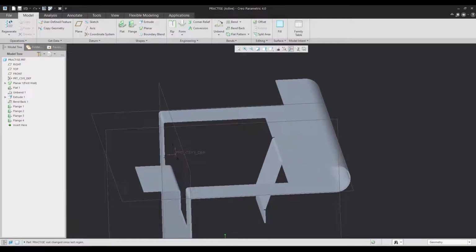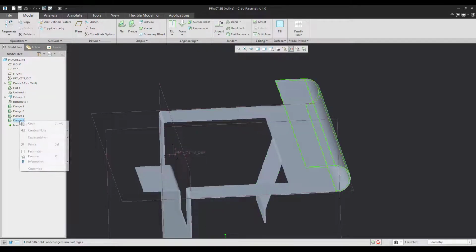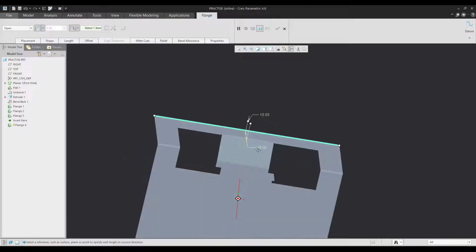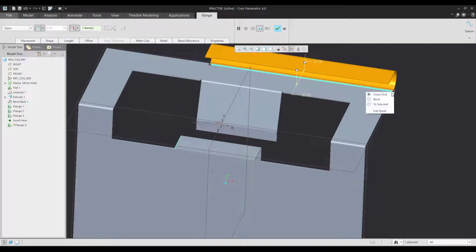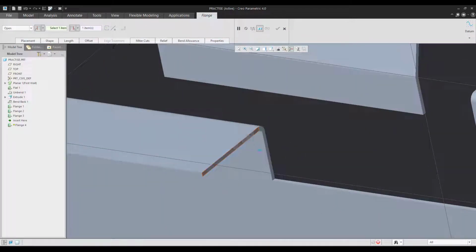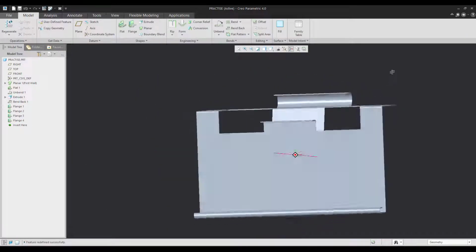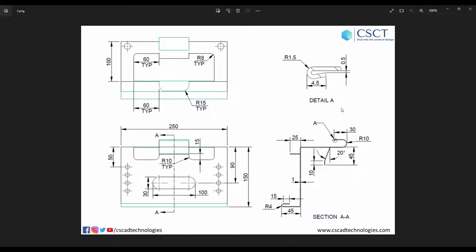Now, the whole wall is not throughout the body, it's just at this location. So, again, you can either give selected to the edge or you can give the dimensions. You want, you can give it selected to this face since they are at 60 only. Same way I can also give a certain edge to give it, or you can actually give a dimension as well. When you go back, you can actually give a certain dimension which is 60, then I will take it as 60. Now, there is also a teardrop, as you can see over here.